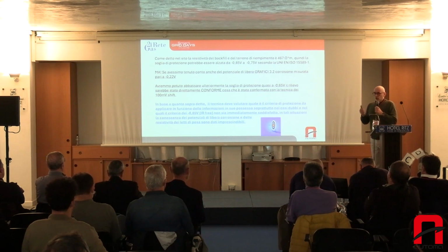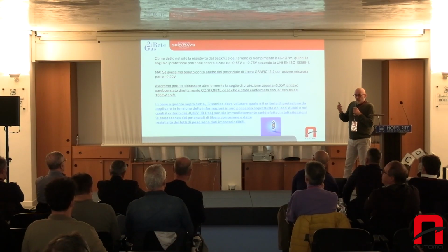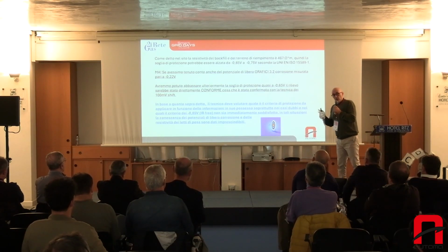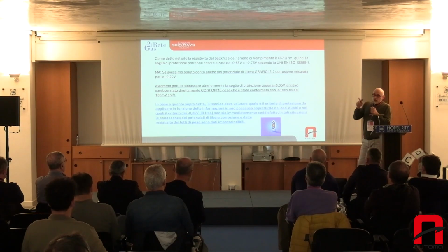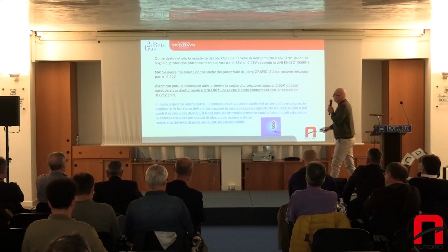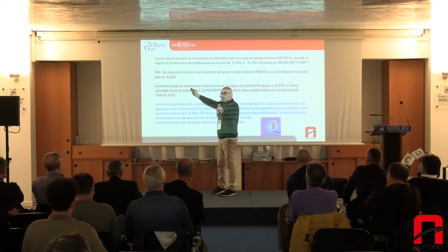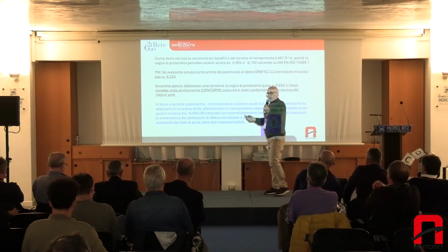After doing all of these tests, I realized I had forgotten something. Checking the initial graph, in that specific point, I had resistivity that would allow me to have 0.75 as a threshold. But there was a free corrosion potential that was minus 0.22.